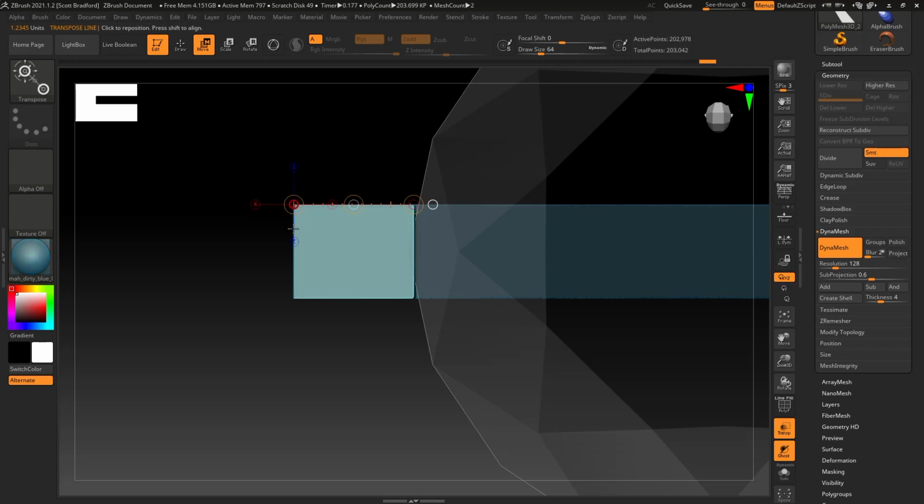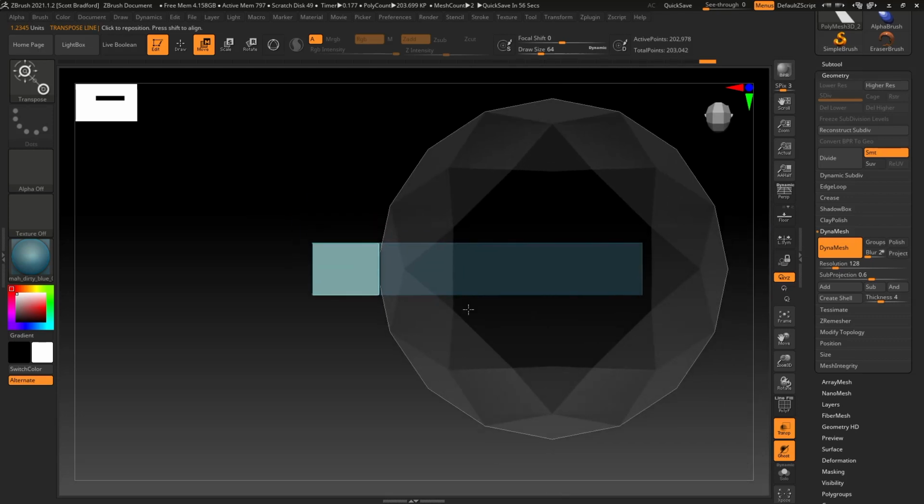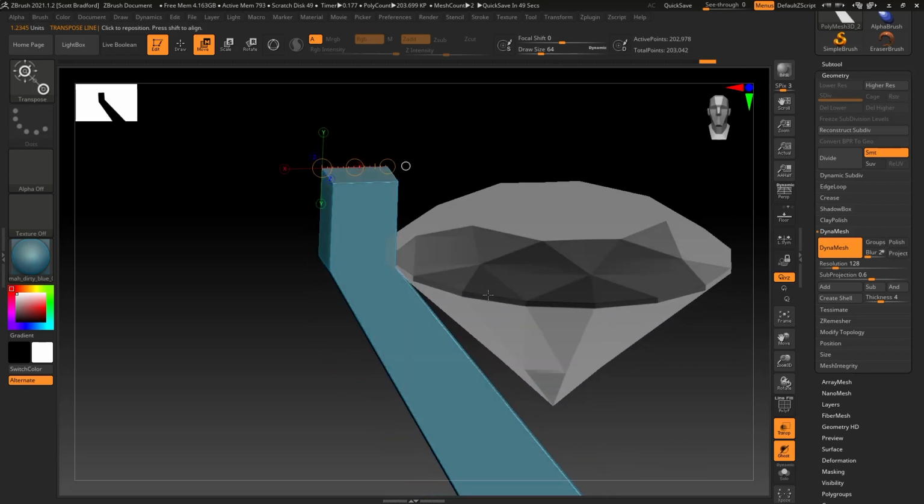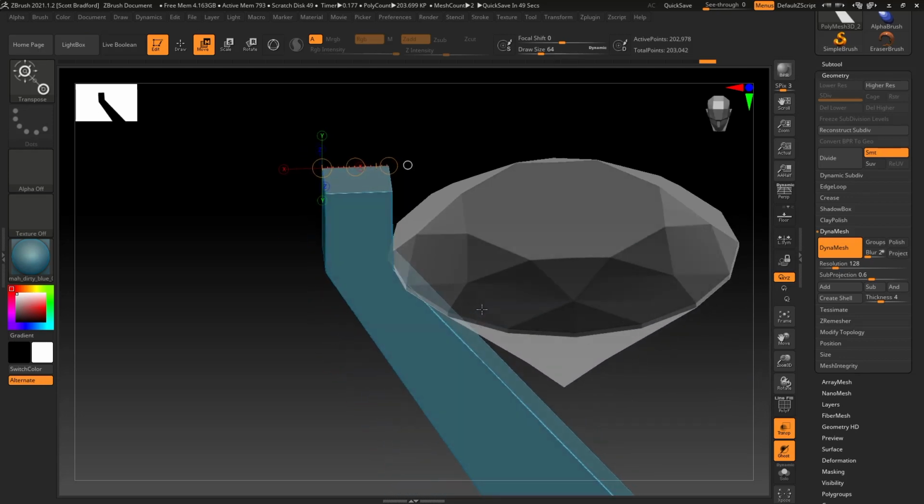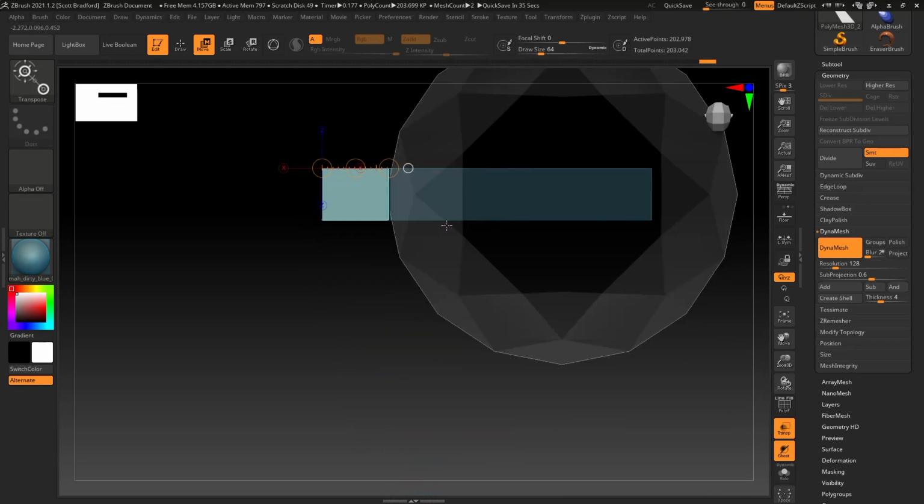Now, one thing you'll notice is that this is more of a rectangle right now. This is 1.2 millimeters in this dimension, but it's still 1 millimeter in this dimension. If you want to make that a bit more squarish, this would be the time to do it. Or if you want to leave it that way, that's perfectly fine as well. It gives you a bit of extra thickness on the backside where all the tool marks are going to occur when you're setting the stone. So totally up to you.